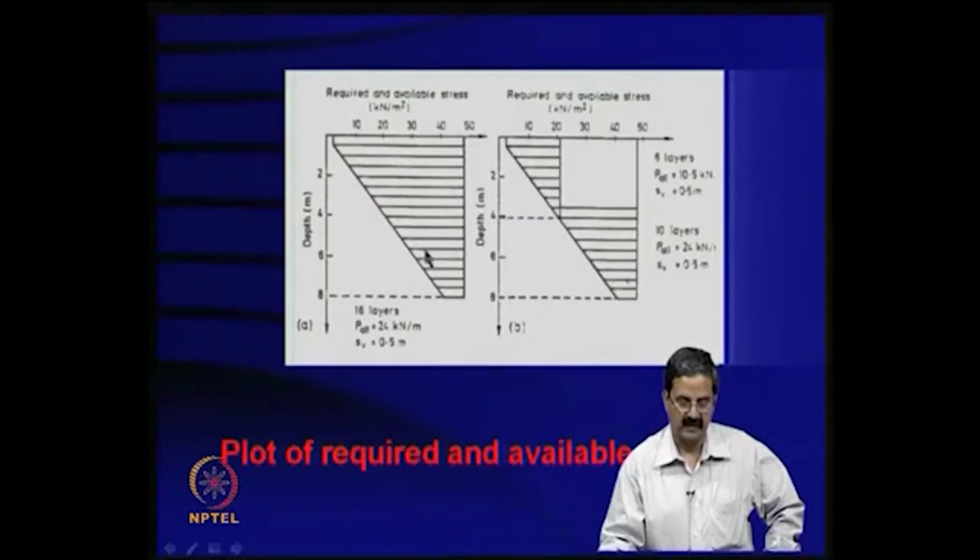Maybe it is fine here up to some level, but you can see that it is all wasted here. If you use a very good material with 24 kilonewtons, it is not worth having 16 layers, it is underutilized. So one way is that you take the 10.5 kilonewton one and then have spacing, and you can put up to some layers wherever it fits.